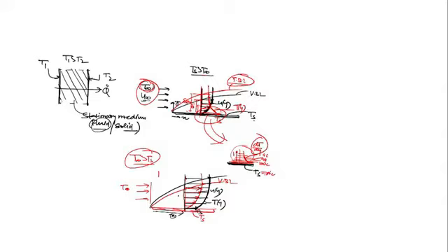But it will not start from 0. That's the more important thing, it will not start from 0, because even at y equal to 0 there is some temperature, that is the surface temperature. Clear, sir? So what happens in the fluid is that the temperature gradient develops, and since the fluid is in motion, that temperature gradient causes heat transfer through convection in the fluid.